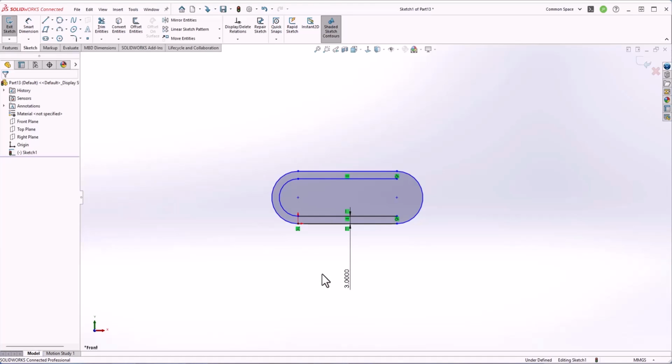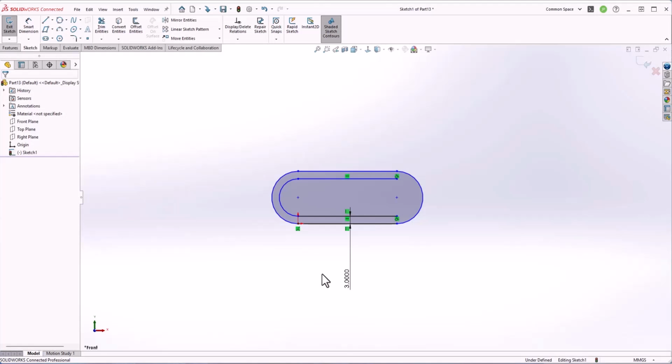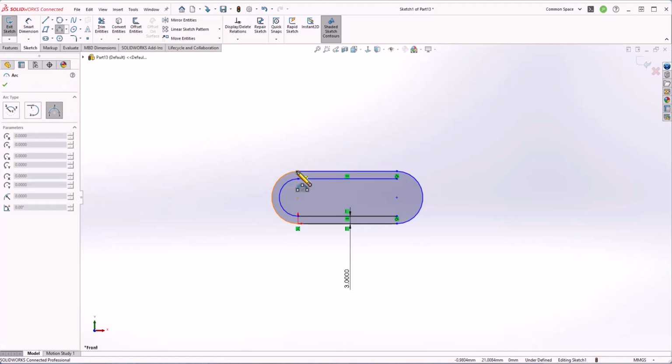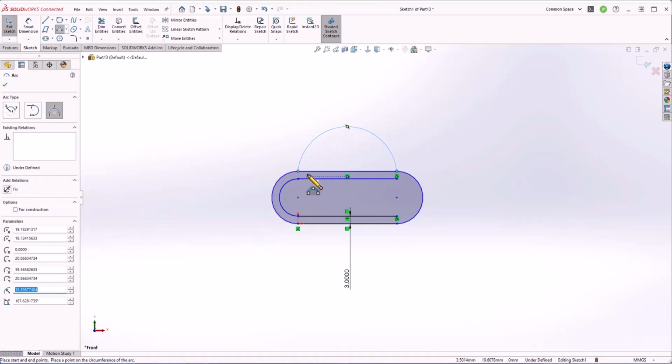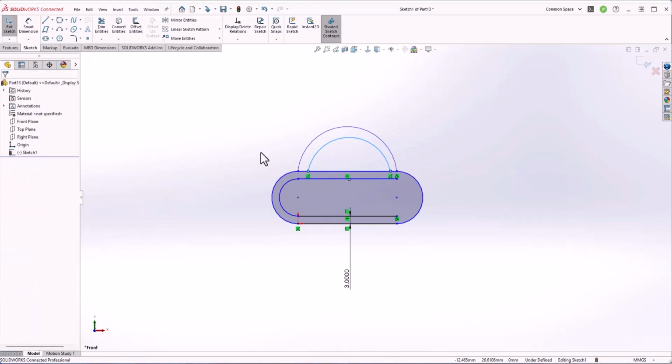Now let's talk about other tools here. So the next one is move and copy. Now these are some of the options that you may end up using quite frequently. So here I'll go to arc tool and I'll just make an arc right here. So using arc tool, we can make an arc, and in this case I'm using 3-point arc. So I'll select first point, second point and third point somewhere here, and I'll repeat the process. So first point, second point and third point maybe somewhere here. Of course the drawing is not very good, that's totally fine. We'll use it only as a reference.